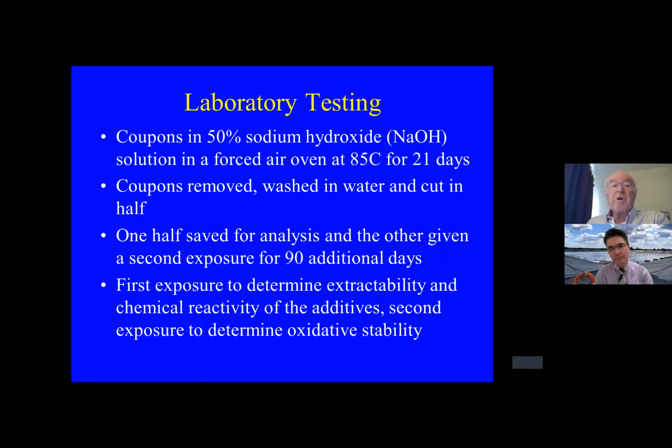These tests were carried out on coupons soaked in 50% sodium hydroxide solution in a forced air oven at 85 degrees centigrade for 21 days. The coupons were removed, washed in water and cut in half. One half was saved for analysis and the other given a second exposure to an additional 90 days. The first exposure was to determine extractability and chemical reactivity of the additives. The second exposure was to determine oxidative stability.